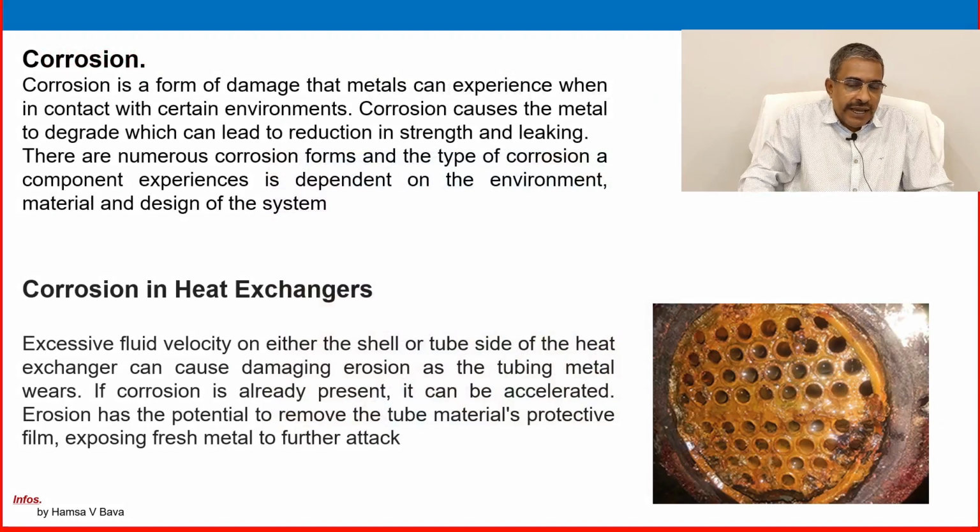As you know, corrosion is a general phenomenon in hydrocarbon operating plants, not only in heat exchangers, but we are discussing heat exchangers today. Corrosion is a form of damage that metals can experience when in contact with certain environments. Corrosion causes the metal to degrade, which can lead to reduction in strength and leaking. There are numerous corrosion forms, and the type of corrosion a component experiences depends on the environment, material and design of the system.